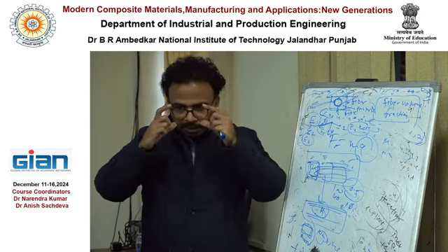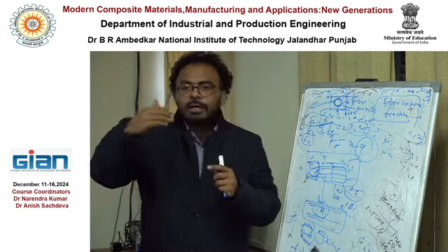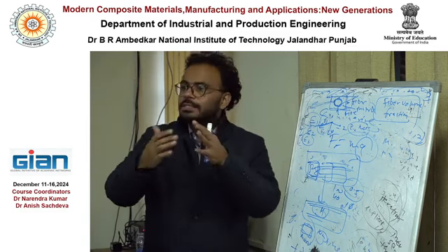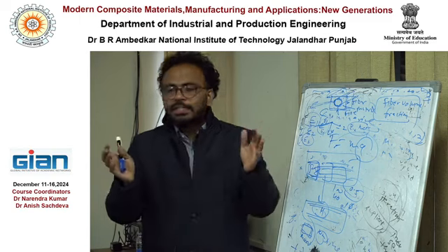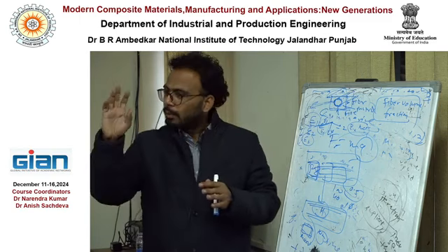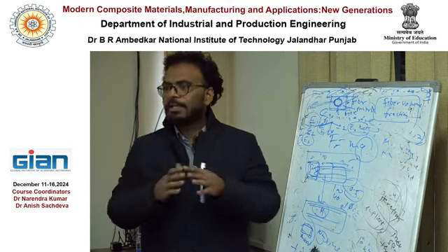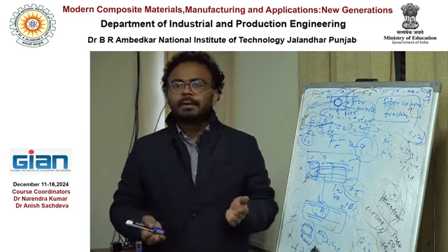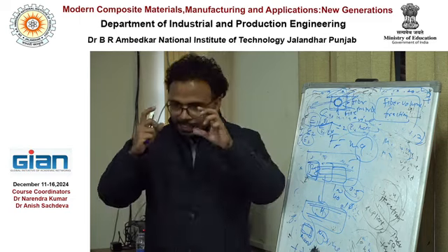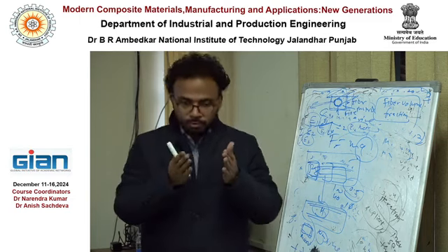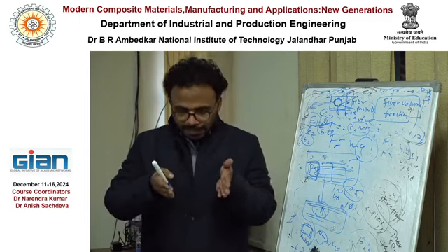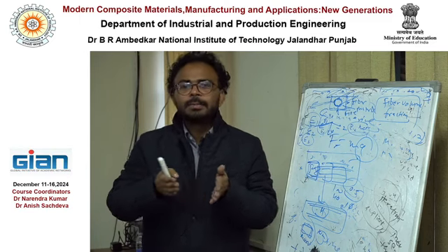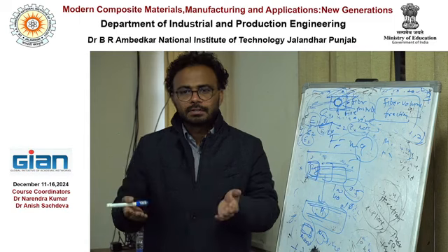If you see by the image that the big part is the repetition of 2 mm, you will create the 2 mm RVE. So this depends, right? If you don't know anything, just create 2 mm by 2 mm by 2 mm or 3 mm by 3 mm by 3 mm, or 200 micrometer, 100 micrometer like this. But generally, if you know by the SEM, or if you manufacture it yourself, you know approximately 100 micrometer or 2 mm or 1 mm is the repetition of the part, right? Did you get my point?